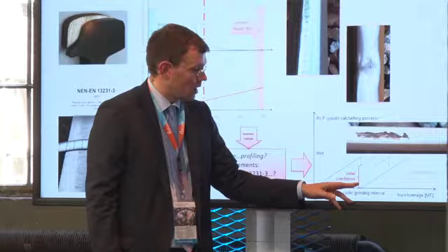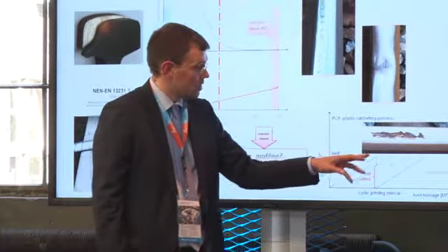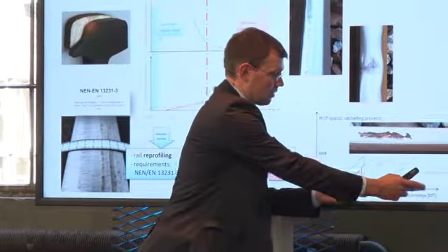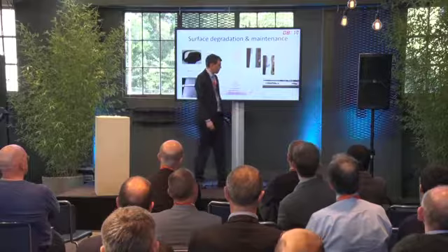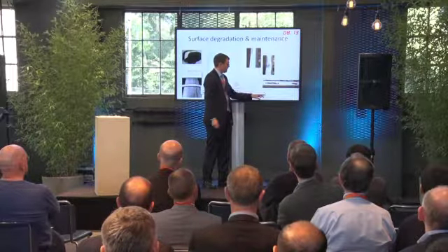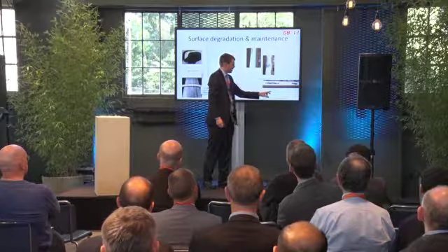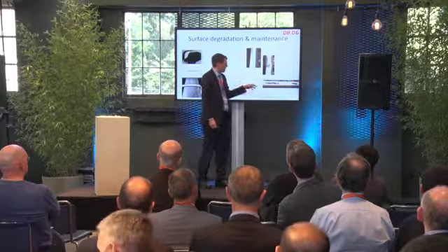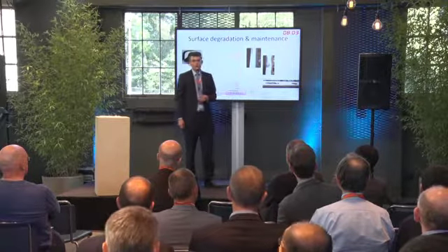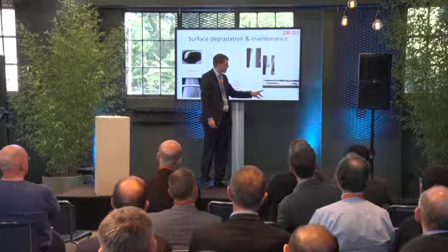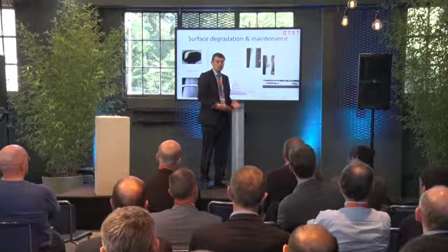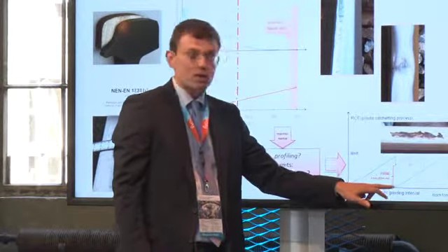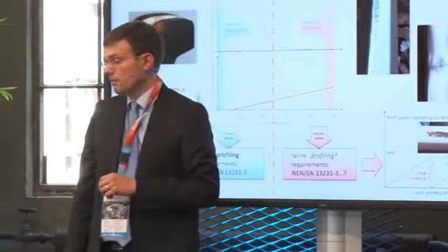And here somewhere are what we can call initial conditions. So when you are able to set back the initial conditions to 0, you again have this tonnage window. When you do this in a less appropriate way, you can shorten the life cycle. And in very bad cases, I think many of you are familiar also with what can happen then, you can get severe spalling. But there is a lot in between. There's a lot in between a case of, I would say, damaging the rail just by the treatment, or setting it back entirely to 0. And these initial conditions, that's the subject of my paper.